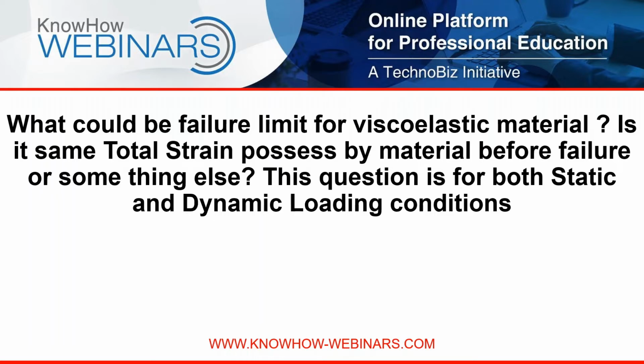Now, again, that would be for a static condition. But when you go for a dynamic condition, a material or a component has always to satisfy some sort of stiffness conditions. So you will do your experimental testing for that. In the first test, you do it on a fresh component. You do a static test and you find the stiffness. Then you do a long-range fatigue test, an endurance durability test. You find out the stiffness again, right?